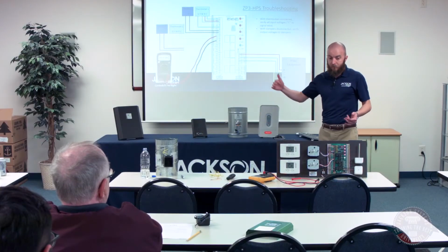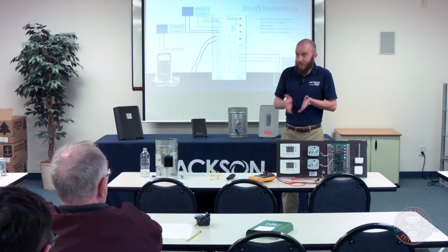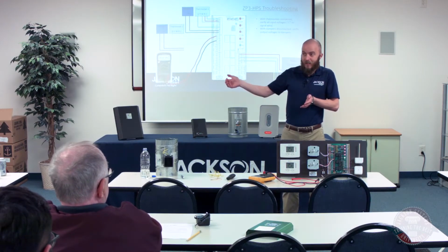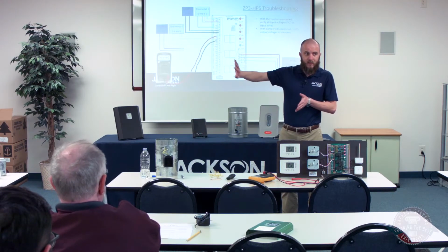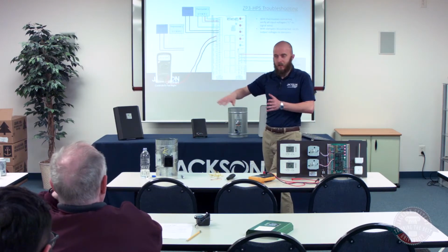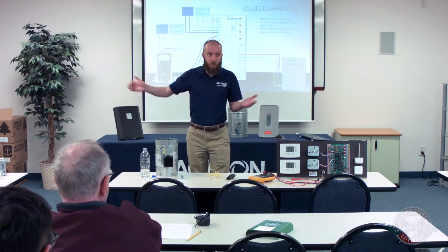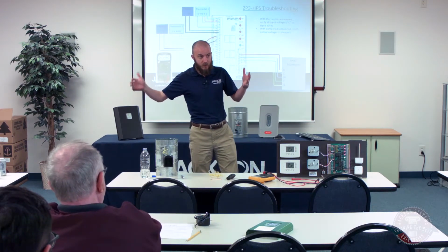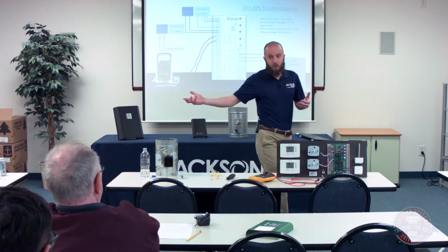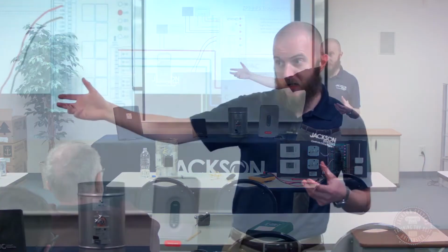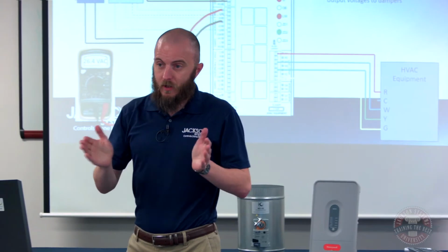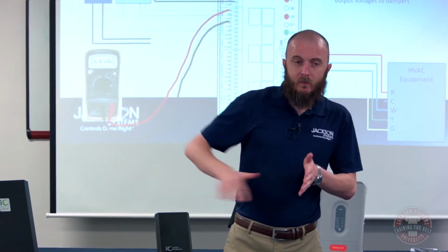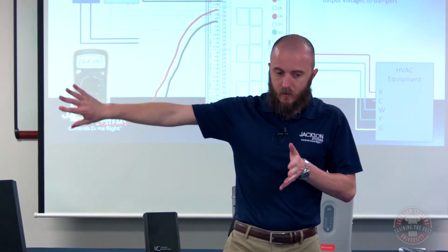All right. If you're not getting the right signals in, if your thermostat says it's calling for cooling but you don't have a Y signal, then you need to take a look at the thermostat side of things. It could be a broken wire somewhere between your thermostat and the zone panel. Could be a problem with the thermostat itself or the thermostat subbase, or some loose wire connection at the thermostat subbase. But if you're not getting the right signal from your thermostat, then look at your thermostat side of things.